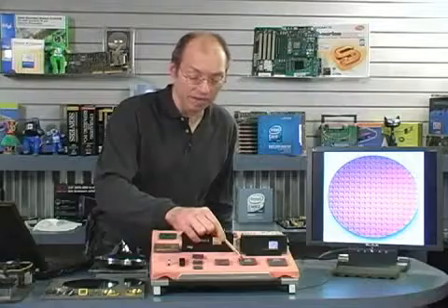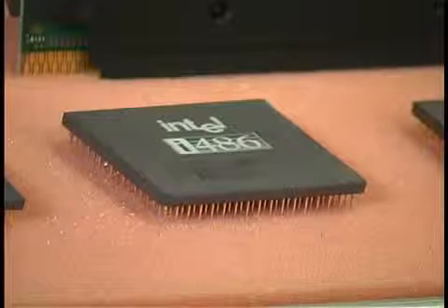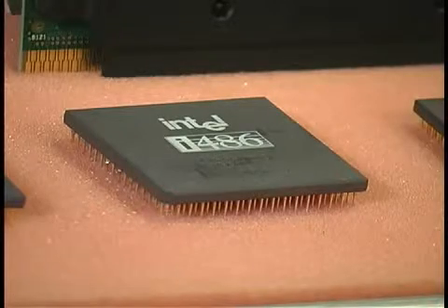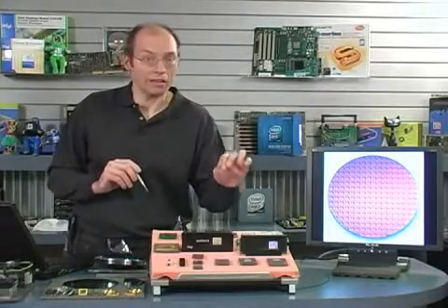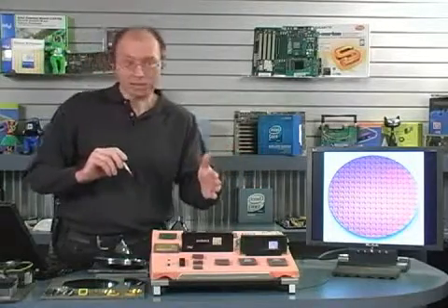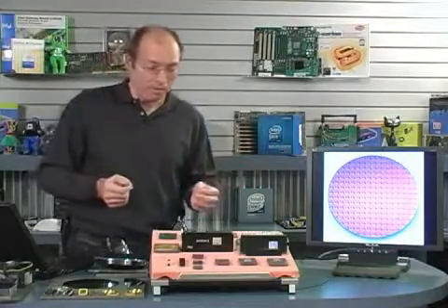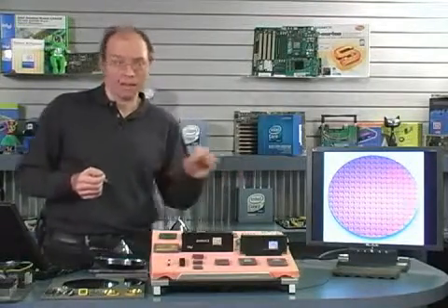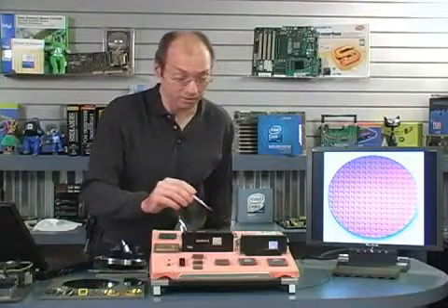Next, we have an Intel 486 processor. The 486 came out in 1989, and this was the first processor to have over 1 million transistors on it. It was about 1.2 million transistors, actually. Several changes happened in that processor. One, it was the first processor that had built-in cache memory. And that was sort of a revolutionary breakthrough because processing speeds had been exceeding the speed of memory chips, at least affordable ones. So by building memory into the processor, it sort of brought along its own little high-speed portable cache buffer of memory, which made things work incredibly faster. So the 486 was a breakthrough.